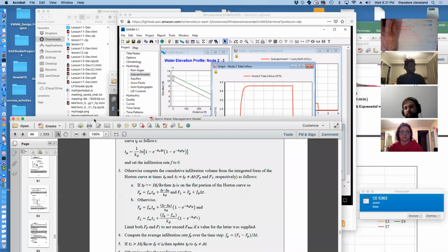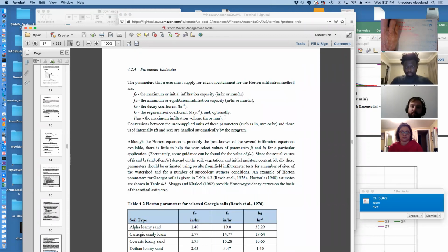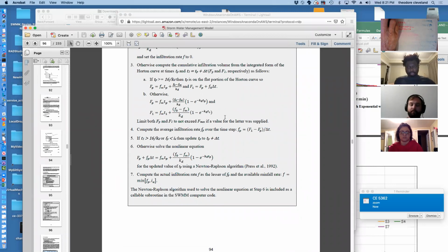All right, so we have reverse engineered that infiltration model. And I personally like the Horton model because it gives me, the modeler, an immense amount of flexibility in describing each of my subcatchments. As long as I can defend my choices of f sub infinity and f sub 0, I like it. In some client situations, they will forbid you to use it because they see the word empirical. They can read too.